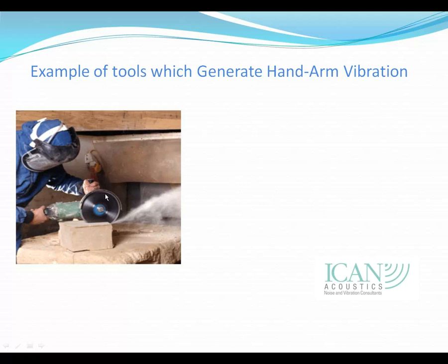Now, just in relation to angle grinders and similar equipment, a lot of the leading manufacturers are putting a lot more design now into the actual handle and decoupling the handle from the machine, in that it's still obviously connected to the machine for control purposes, but there is vibration decoupling in there, all in the interest of protecting the employee and reducing the exposure to hand-arm vibration.